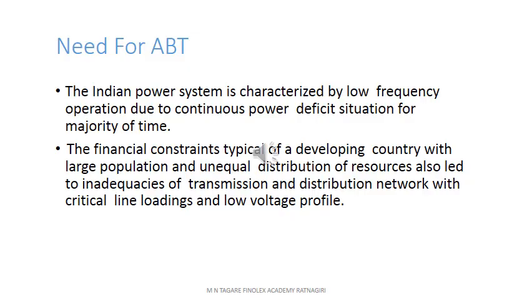All those mechanical governors have been replaced by electronic fast acting governors. They are very fast: they sense that there is a fall in speed and immediately admit more mechanical input to the rotor, thereby restoring the frequency to the normal 50 Hz, keeping the speed of the alternator at 1500 RPM or whatever the intended speed is. They maintain that speed so that we get a stabilized frequency.